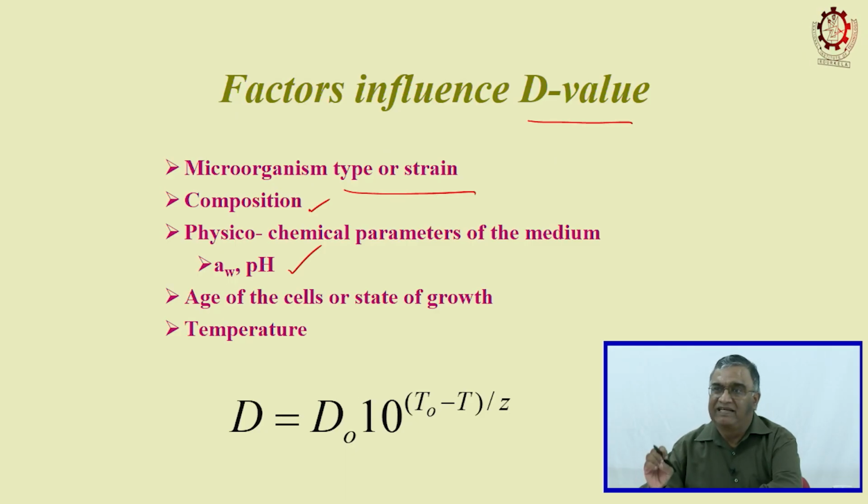Instead of 1 minute at the same temperature, it may become 0.7 minutes or 0.6 minutes because it is an acid environment, or it may even be completely inhibited. So, you have to consider that. And then you also have to consider the age and stage of the cell growth, but normally when you are doing processing in an industrial environment, you may encounter what they call wild bacteria.